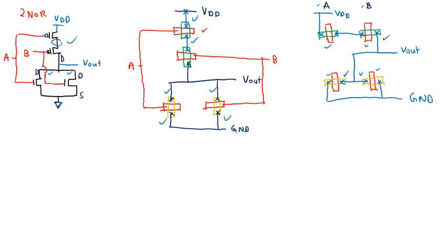To optimize this design, you just extend the PMOS polysilicon here, and then the N diffusion, you just merge both, so that you do not need to have this metal in between. Okay, I just remove this one, so no need to have that.